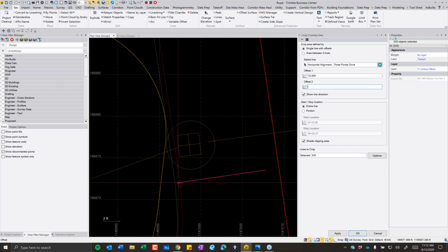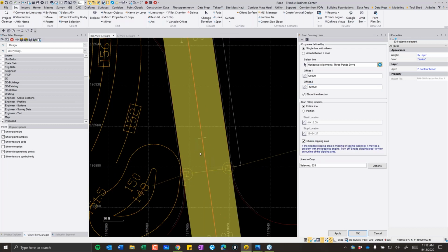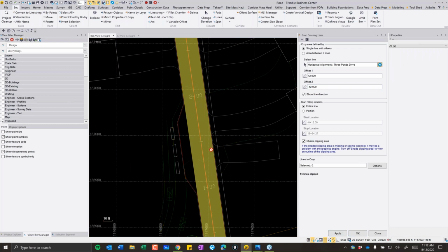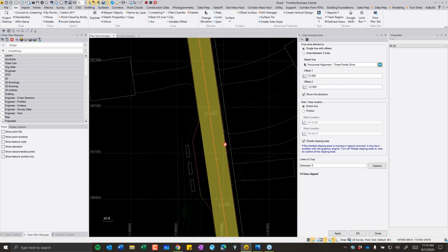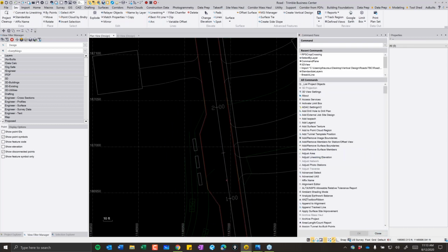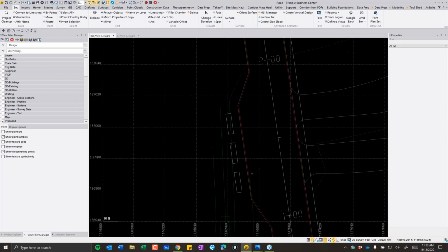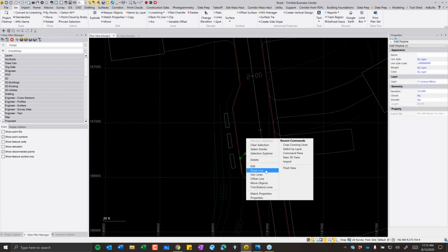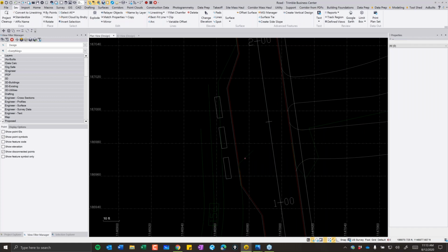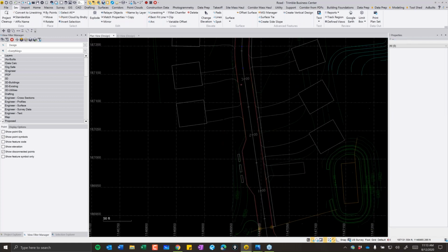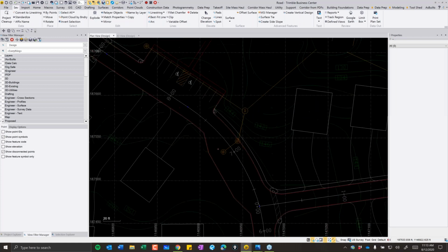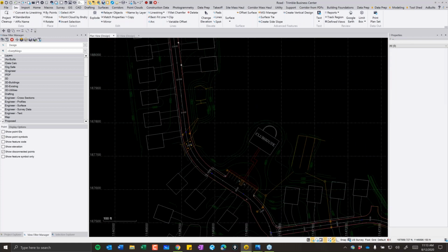You can either click 2 lines that encompass the line work you want to crop, or you can actually set offsets. This is nice because it quickly allows you to clean up the contours on the edge of pavement. A lot of times the engineers will give you this, but because of the profile, they may not take into consideration the vertical curve, or when they smooth out the contours, it's not really a good representation of what the roadway is doing. I always trim those out.